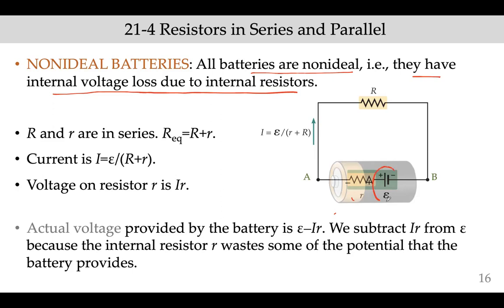Epsilon here is the voltage, or the electromotive force, that the battery creates. You get the voltage from the terminals, but before it comes to the terminals, there is some internal resistance in the battery. Again, it may be caused by imperfect chemical reactions that consume energy or produce heat, or maybe the cables or metals within the battery also create some resistance. Let's show it with lowercase r.